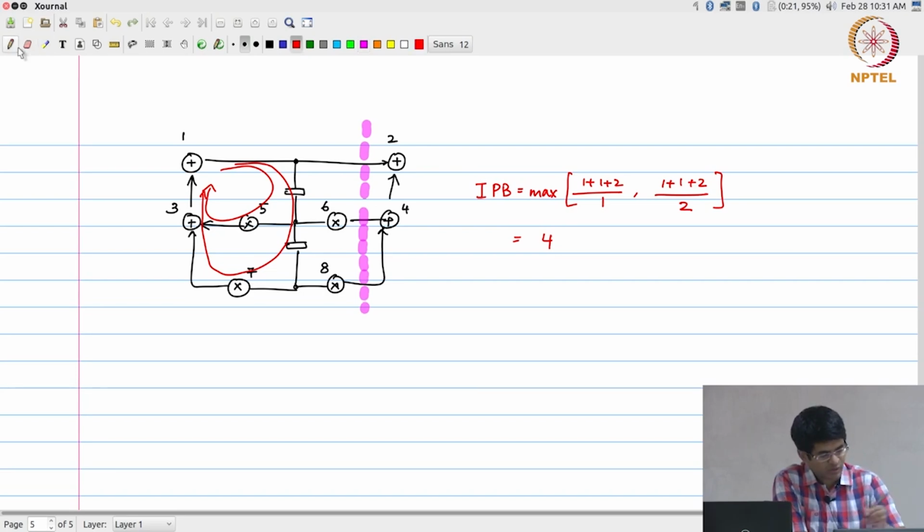After I have done that, I put delays over here. What does my directed acyclic graph now look like? The directed acyclic graph is ultimately what I am interested in for my scheduling. So what it would look like after I have done this magenta cut set is, now operation 4 also does not have any dependencies. All the others remain the same.